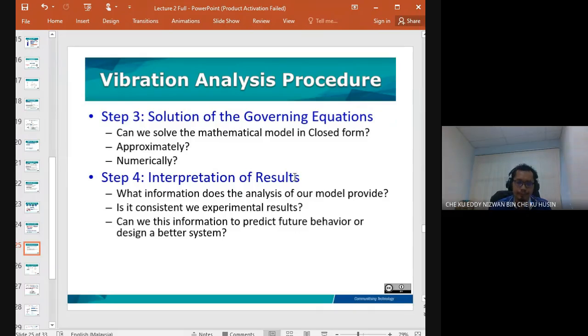Okay. Especially when you deal with FEA, finite element analysis. The most important thing, you must develop the equivalent CAD model. And then you must input the correct material properties, and then the boundary conditions, whether they are equivalent, because sometimes you use a fixed boundary condition and the actual is not fixed. There is still motion, so it's not totally fixed. So that's why you have to do the modification.